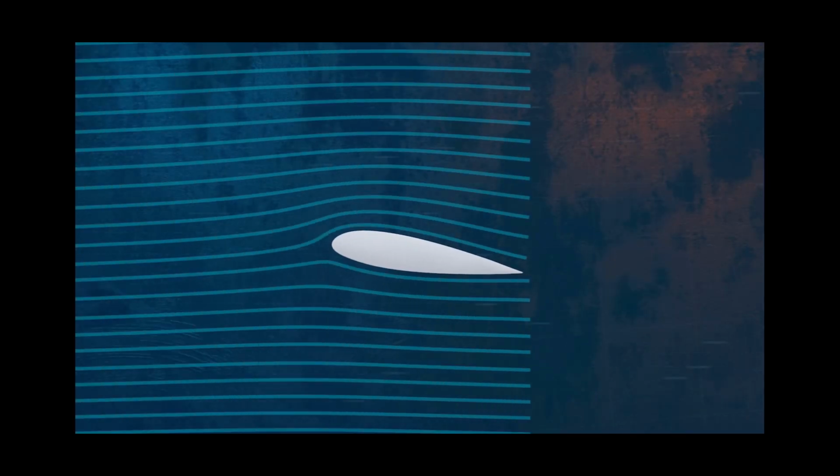Aerodynamic explanation. The wind turbine rotates based on Bernoulli's principle, which focuses on the velocity of fluid. If we look at how fluid flows around the airfoil, we can see that close to the leading edge, there is a point where the fluid velocity is reduced to zero. This is called the stagnation point.